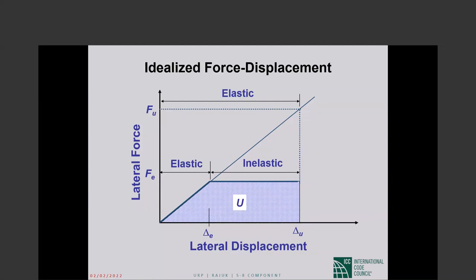Now, many observations and also a lot of analytical work has shown us that the total displacement suffered by the structure, total displacement delta sub u, is about the same, not precisely the same as shown in this idealized picture, but about the same whether structural response is elastic or inelastic to various degrees.